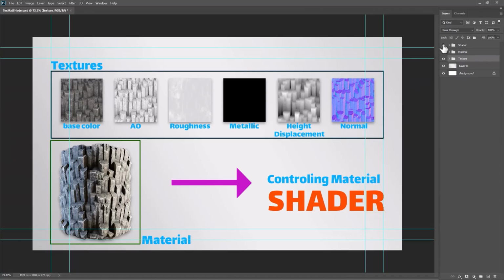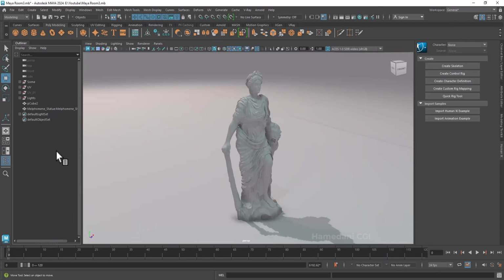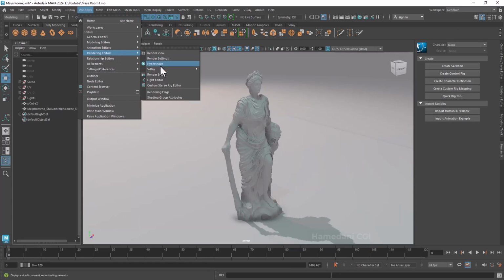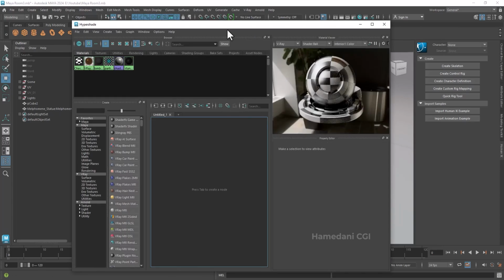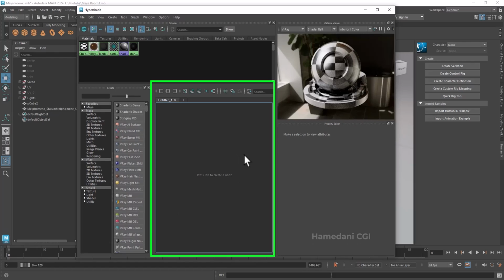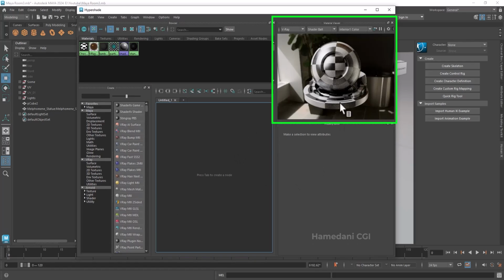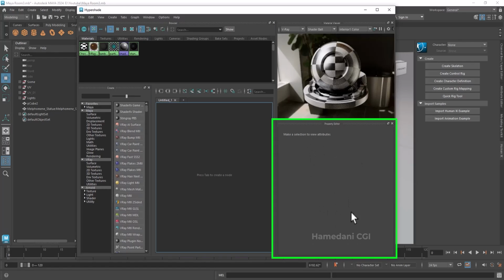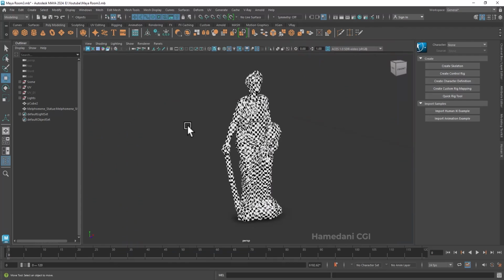Let's go inside Maya and I show you how to create a material and how to edit the material. For create and edit material, we use Hypershade from here, or from Windows menu, Render, Editors, and Hypershade. Here you have panels. Browse, you see created material, you create material, texture, or utility, graph network editor for material, material preview, and property editor for control parameters of shader, and texture utility in Hypershade. For create material, you have to go first to Hypershade and right click.